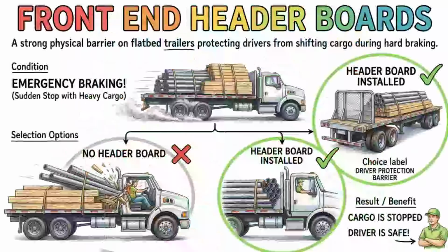Finally, you must be aware of the specific rules regarding bus braking systems, especially the brake door interlock. Many modern transit buses are equipped with a brake interlock system that automatically applies the brakes and holds the bus in place whenever the passenger doors are open. This fantastic safety feature prevents the bus from accidentally rolling while people are boarding. However, examiners will want you to know that you should never use this interlock system in place of your actual parking brake when you secure the bus at a terminal.